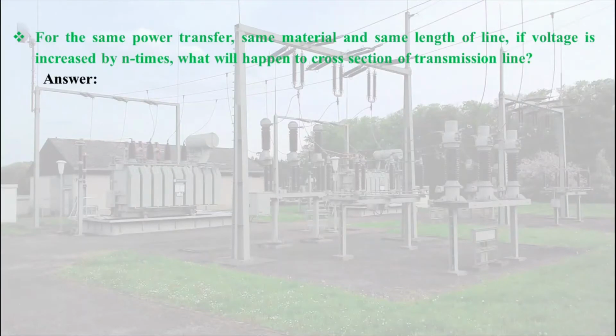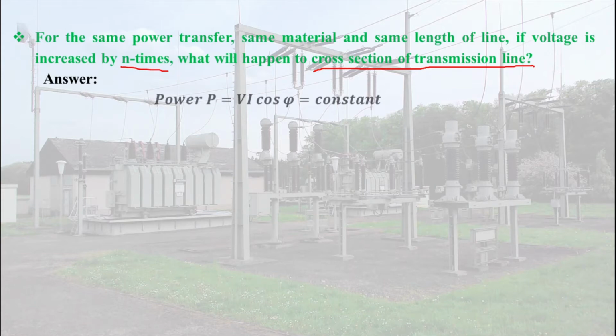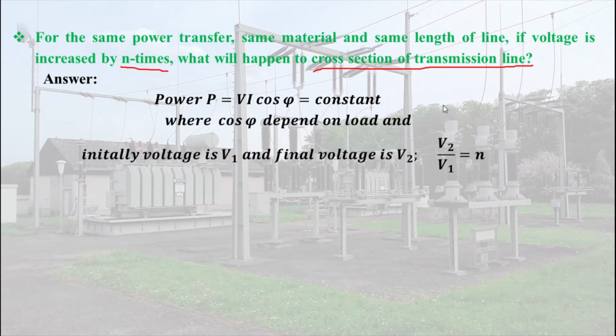First question is, for the same power transfer, same material and same length of line, if voltage is increased by n times, then what will happen to the cross section of the transmission line? So here power P is constant. So we can write P = VI cos phi, and it is constant. Now voltage is increased by n times, meaning initially voltage was V1 and finally it becomes V2. So we can write V2/V1 = n.